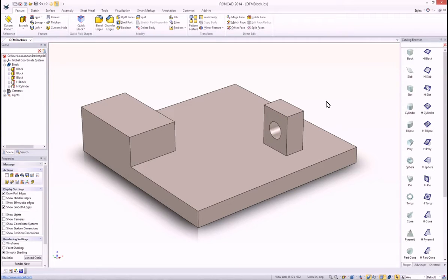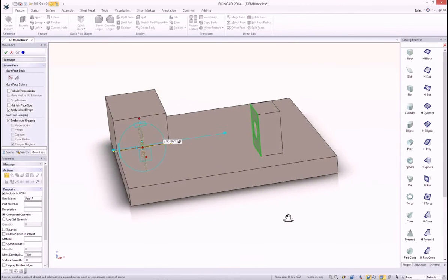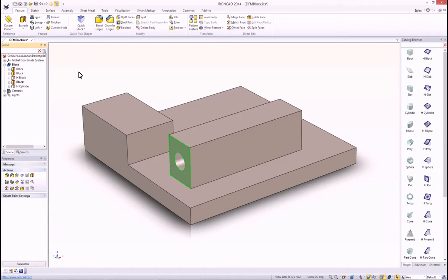And at this point, we would like to go ahead and make a direct editing change to our object in IronCAD. And how we do that is basically we select down to the face level in IronCAD, and enable our positioning tool, which is called the triball, which allows users to simply push and pull handles to precisely locate their object, or their face in this case, to the desired location. As you can see, we're about halfway through on our object, and we can go ahead and apply our direct modification. And in this case, IronCAD is very intelligent and gives the user a predictable result.